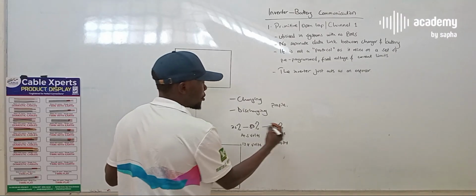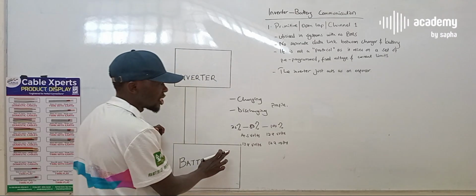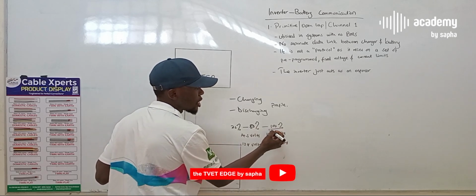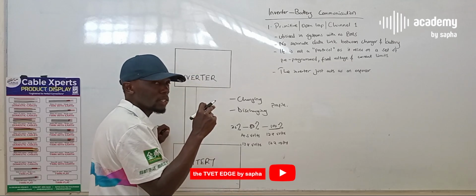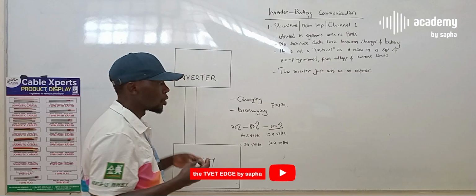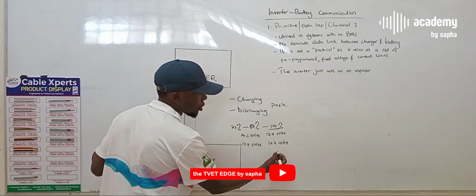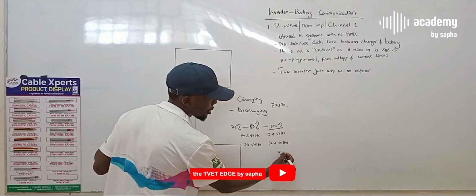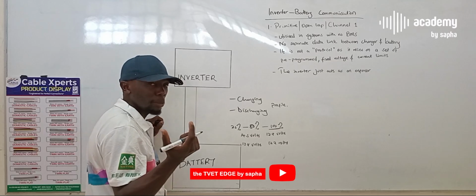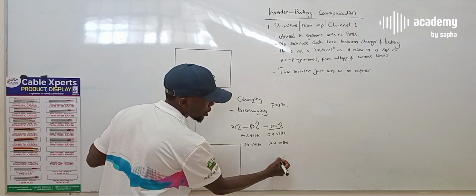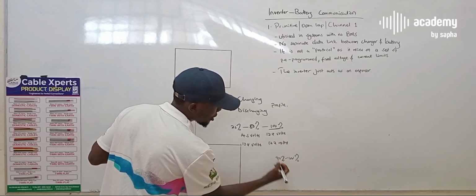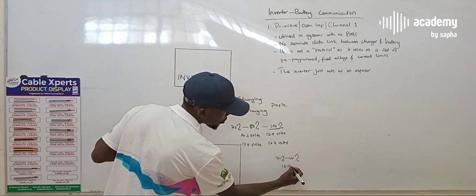And then if this battery is not being discharged or utilized, you'll find that it will not maintain its state of charge at 100%. It will start discharging slowly as the chemical reactions within the battery happen. So for you to maintain it at 100%, or let's say above 95%, you will need to be pushing a very small amount of voltage to maintain it between, let's say, 90% to 100%. So probably in this case, you'll just be pushing around 12 volts.